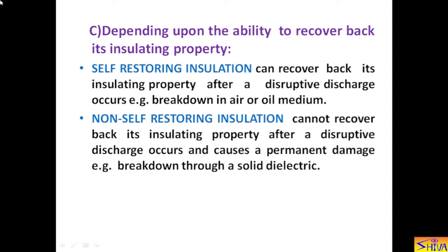Next is non-self-restoring insulation. That is the insulation which cannot recover back its insulating property after a disruptive discharge occurs and causes a permanent damage, that is breakdown through a solid dielectric. So if we are using solid dielectric and a puncture occurs, we cannot reuse that insulation. So that is non-self-restoring insulation.